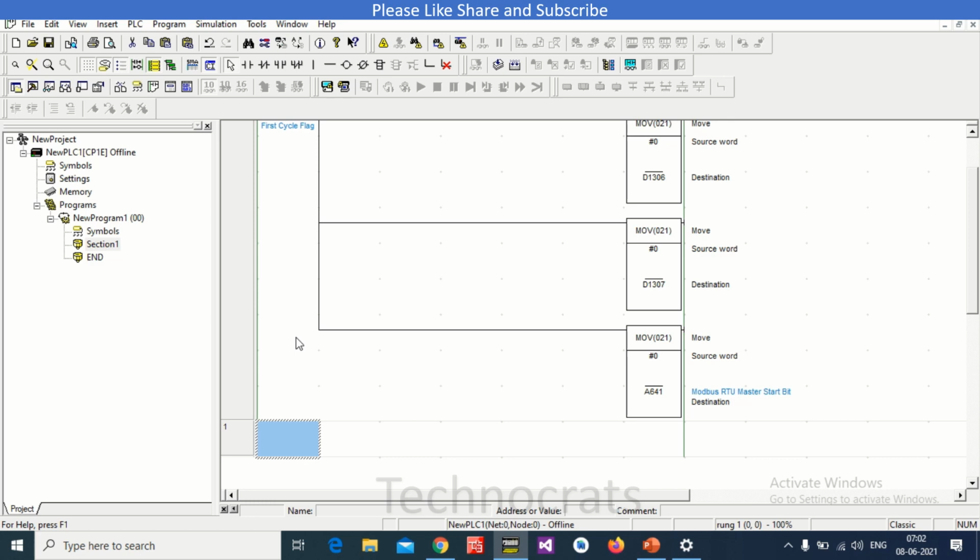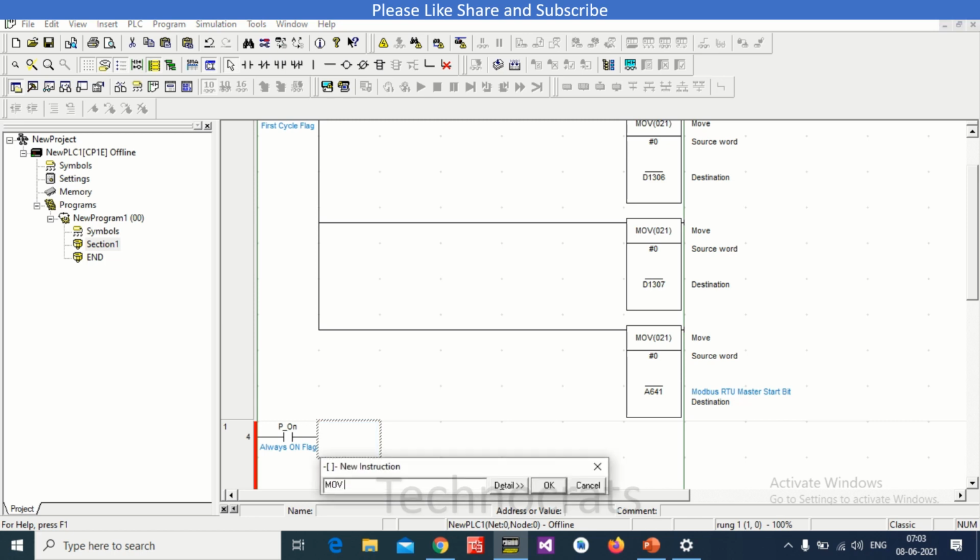So let me write W. We can use P_On. Like MOV, I am using 1 as your slave station, D1300. It is your slave ID of your inverter or any other device you are using.